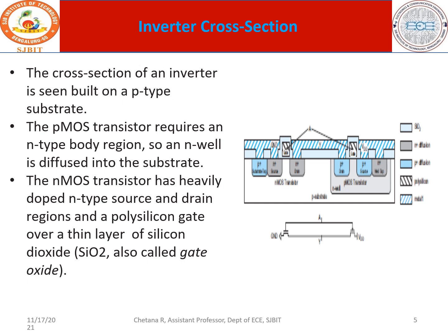The PMOS transistor requires an N-type body region. So an N-well is diffused into the substrate. This is how an N-well structure is created, and with respect to dimensions, normally this is 6 micrometers deep. So identify the regions to create the well structure and do the necessary dopings. On the P substrate you are doing N diffusion, and that in turn is nothing but your N-type well.